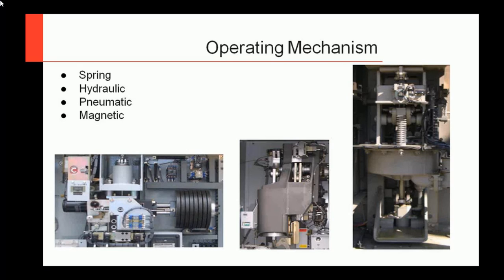The reason they do this is you're never without the ability to trip. If there's one thing this circuit breaker needs to be able to do, it needs to trip on command. You need to be able to at least close and immediately follow with an open to interrupt that fault, in case you close in on a fault.